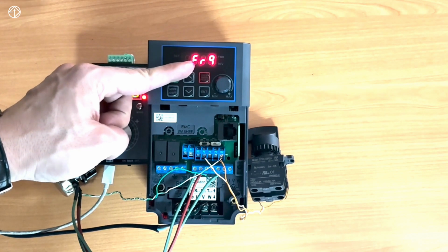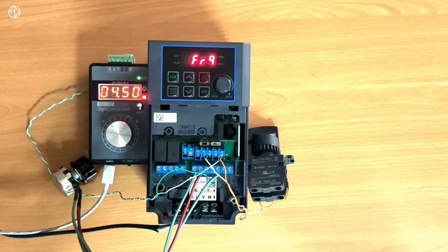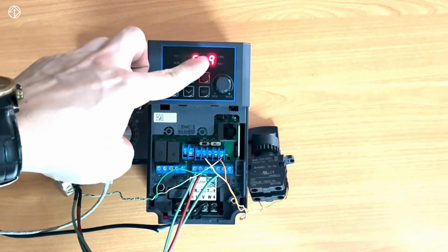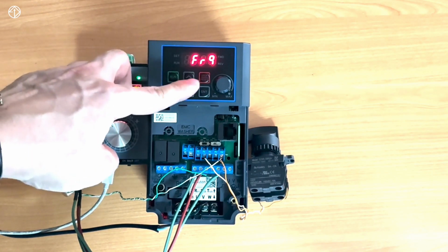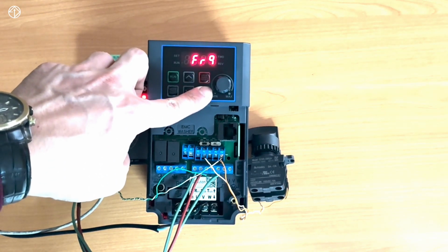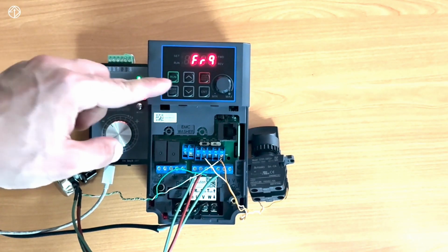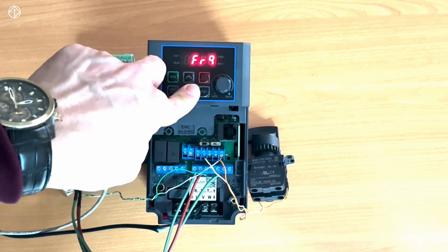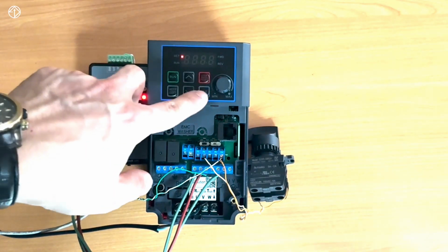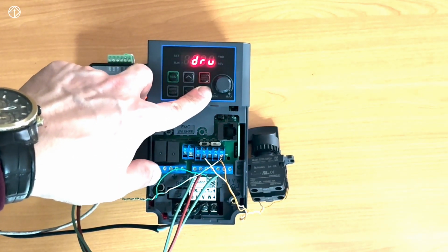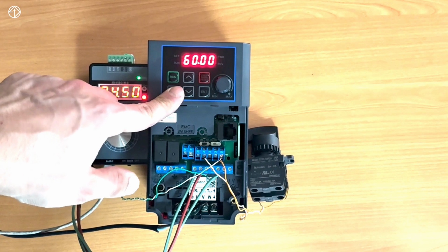Here we want our local mode, meaning if our digital input is inactive, the FRQ parameter, which is the frequency reference in local mode, should be set to 2, so the reference comes from the 0 to 10 volt potentiometer. For the DRV parameter, in the main group related to local mode, we set it to 0, meaning the start-stop command comes from the keypad.